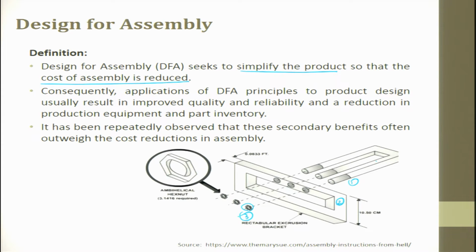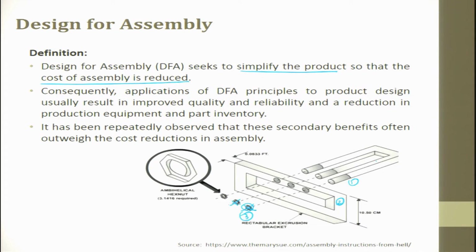If I wanted to apply design for assembly and try to eliminate the parts, what I will do is eliminate these nuts and make the threads internally inside the part. So, now the bolt is getting fastened to this base without using the nut. So, you have reduced a part and this reduces the failure of the complete product.